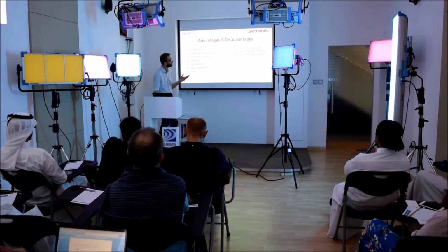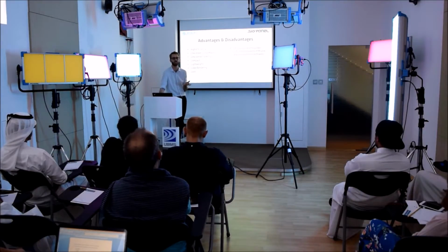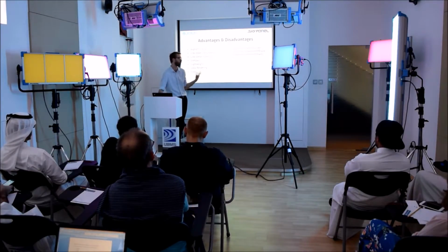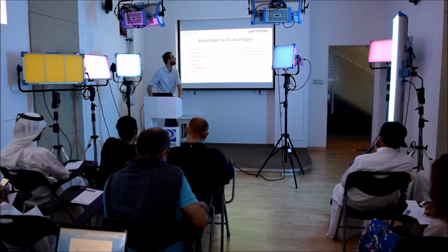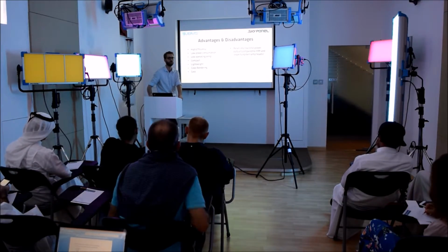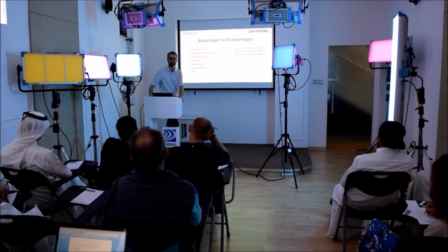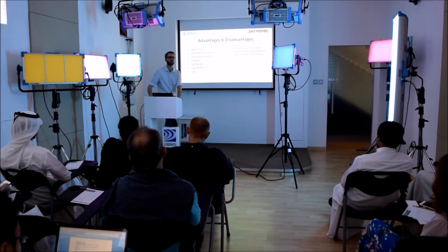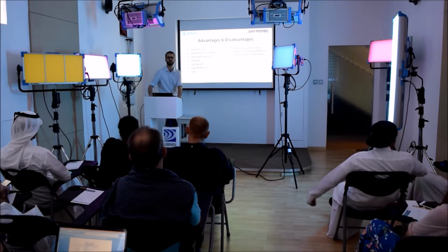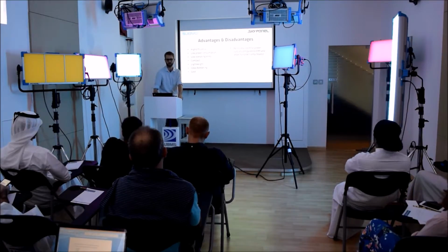So disadvantages, really one of the only disadvantages of LED lighting in general at the moment is that they still have relatively low total power output. LED lighting is getting more and more powerful in terms of punch, in terms of light output. But when you need really, really bright light sources, LEDs, technology-wise, are not going to cut it yet. You're still going to need to be looking at HMIs and things when you need a huge amount of punch. But they're getting brighter all the time.